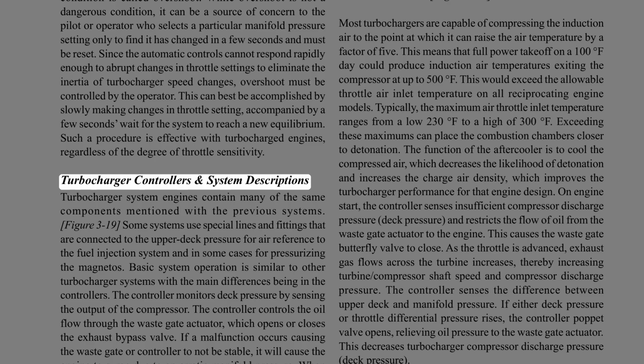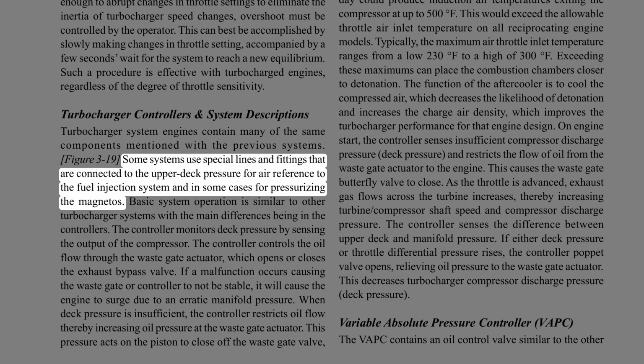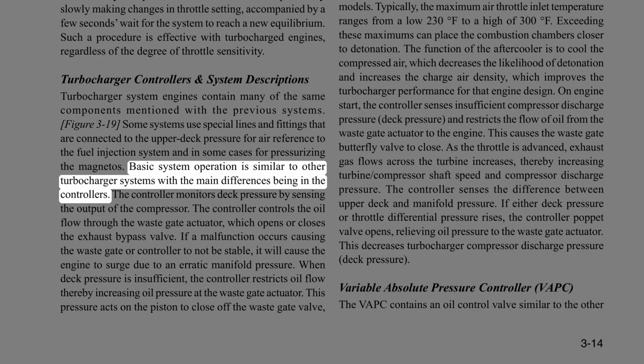Turbocharger controllers and system descriptions. Turbocharger system engines contain many of the same components mentioned with the previous systems. Some systems use special lines and fittings that are connected to the upper deck pressure for air reference to the fuel injection system and in some cases for pressurizing the magnetos. Basic system operation is similar to other turbocharger systems, with the main differences being in the controllers.